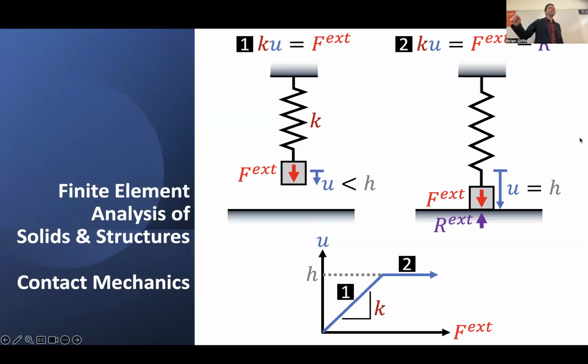All right, so today we're going to begin our discussion of contact with a simplistic overview of contact mechanics from very basic principles, where we'll spend a lot of our time talking about these very simple one-dimensional idealizations of contact constraints, how they appear in the format of solving mechanics problems, as you're previously already familiar, and how they relate to basic mathematical principles of constrained optimization.